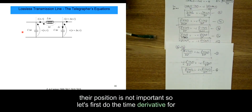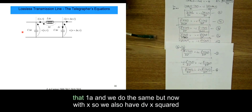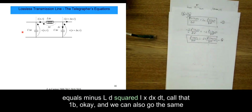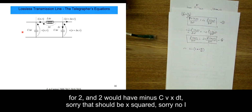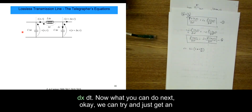So let's first do the time derivative for equation 1. It'd be d squared V(x,t)/dx dt equals minus L d squared I/dt squared. Call that 1a. We do the same but now with x, so we have d squared V/dx squared equals minus L d squared I/dx dt, call that 1b. We can also do the same for 2: minus C d squared V/dt squared, that's 2a, and then d squared I/dx squared, 2b.